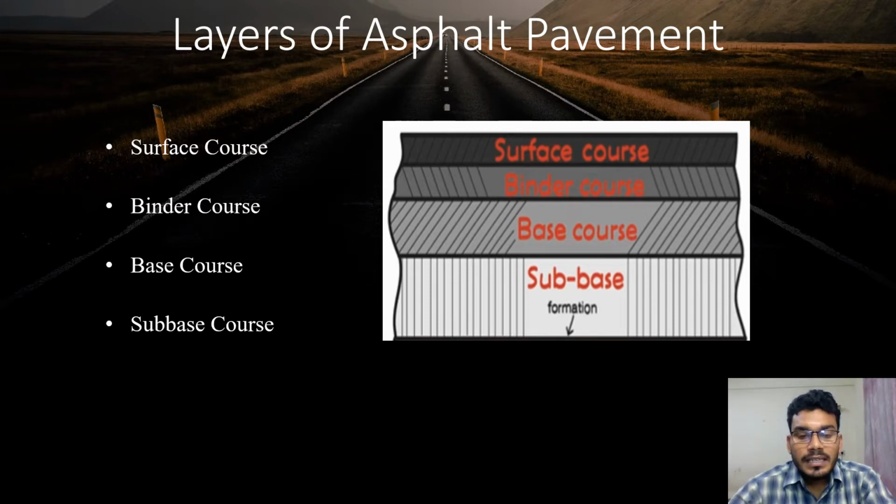The last one is the subbase course, the layer between the base course and the subgrade. It functions primarily as structural support, but it can also minimize the intrusion of fines from the subgrade into the pavement structure and improve drainage.